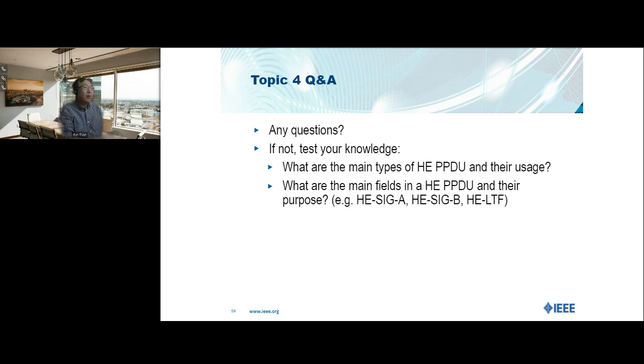If you talk about the 0 GI, which has no power in the GI part, 0 GI is not used for 11ax data communication. There is something called 11az, which is for ranging, enhanced ranging. In 11az, for security purposes, they introduce something called 0 GI. By the way, you still have a GI interval, they just don't transmit any power in that region.